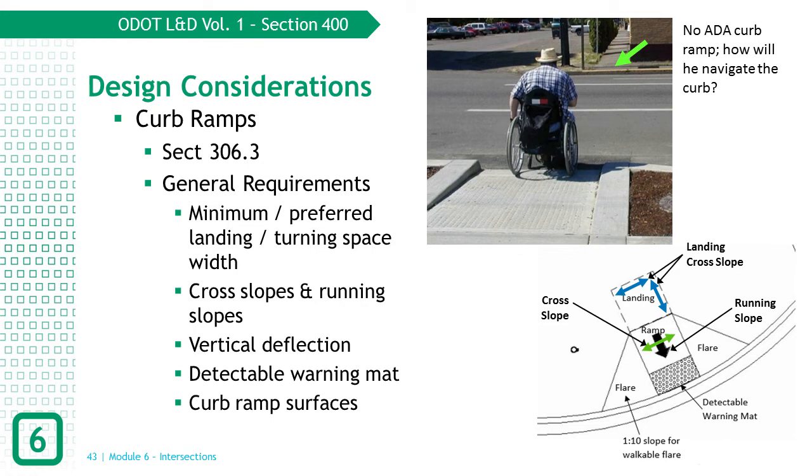Curb ramps are required to have a detectable warning mat. These mats alert visually impaired pedestrians that they are leaving a pedestrian facility and entering a roadway. The detectable warning surfaces shall be placed per the ADA guidelines or ODOT standard construction drawings and be a contrasting surface color. Note that a sidewalk that is flush with a roadway surface does still require a detectable warning.